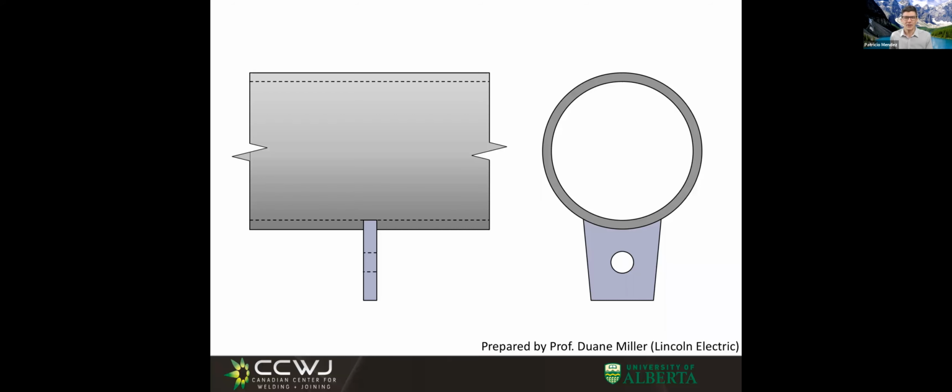How about this? Okay. If we put the plate, instead of aligned with the pipe, we put it transverse. We can put the weld there. But this is going to be another very bad idea. The load is resisted by the stiff part of the pipe.